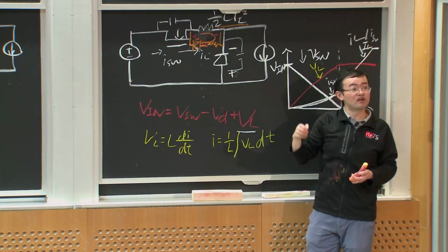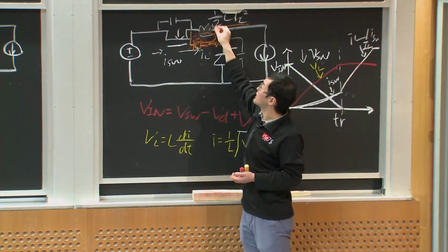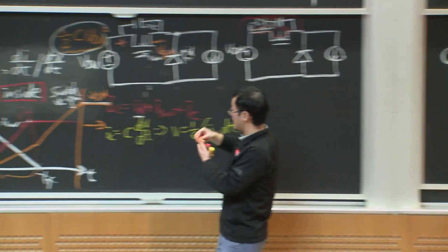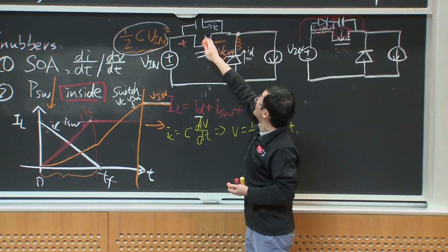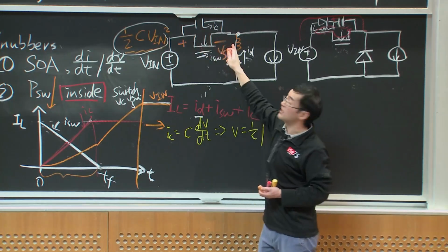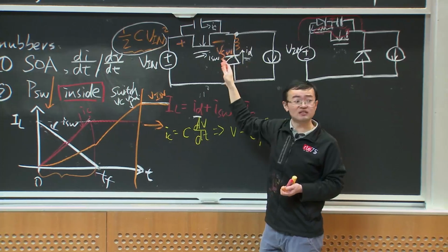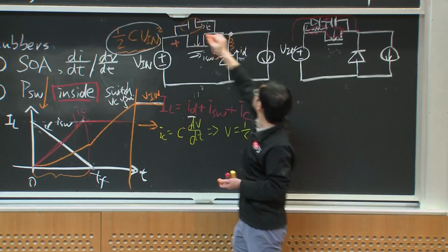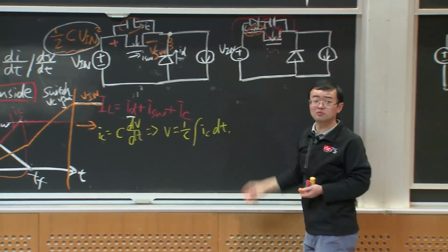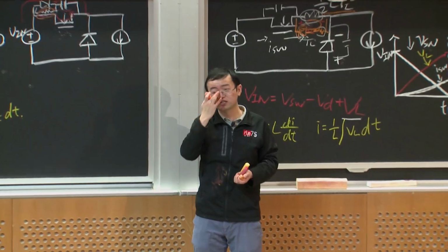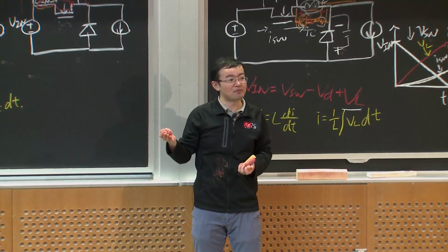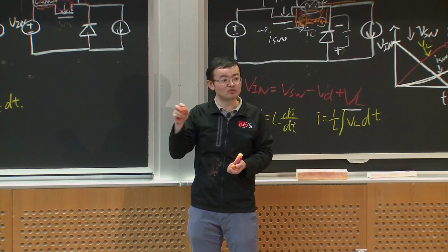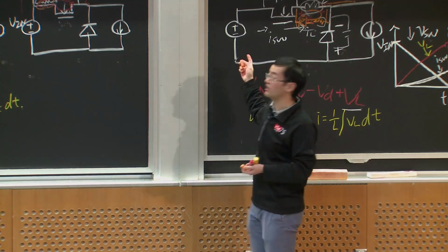In the textbook, there's a chapter about how we choose this inductor value and how we choose this resistor value. Similarly, we still have the parasitic stray inductance here, and in some cases this capacitance will still resonate with it. This is something we cannot avoid, but we can choose circuits or elements, like how we choose this capacitance and this resistor, to improve it. If you imagine a second order system, we can have critically damped, over damped, or under damped. So we can purposely put in a small resistor to dampen that out. But this is something we need to pay attention to as a trade-off.